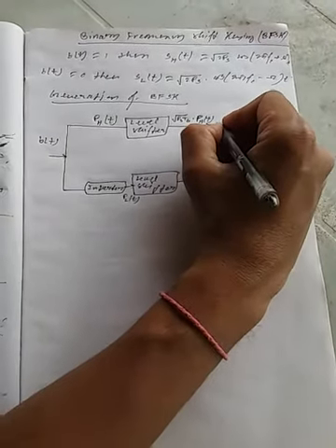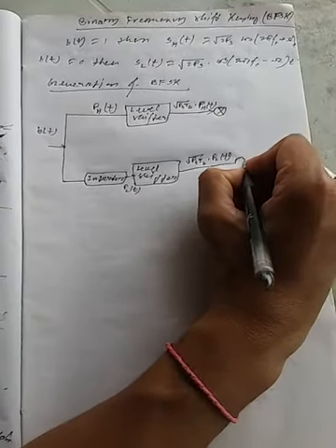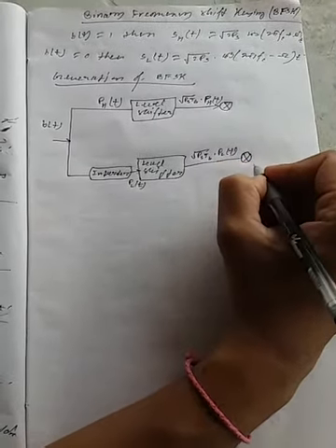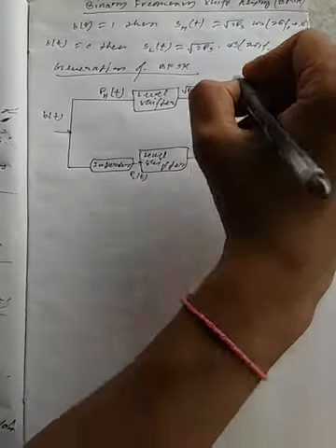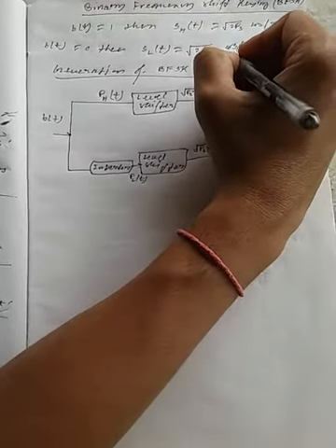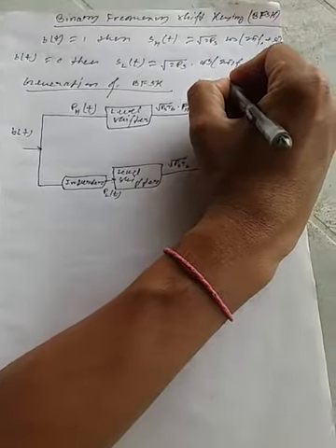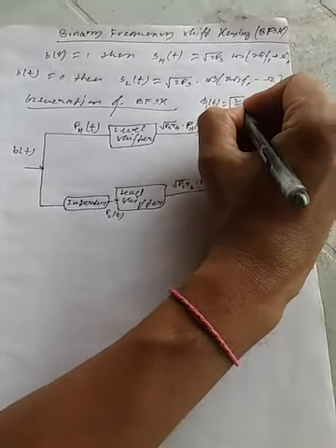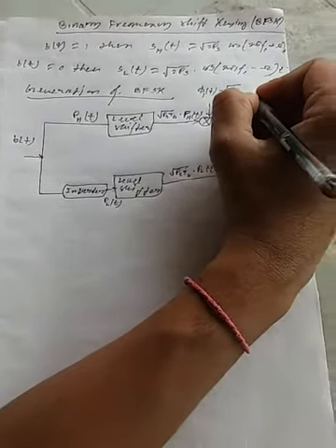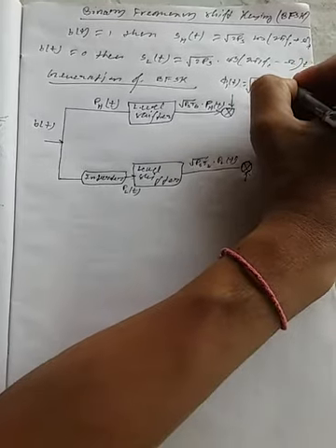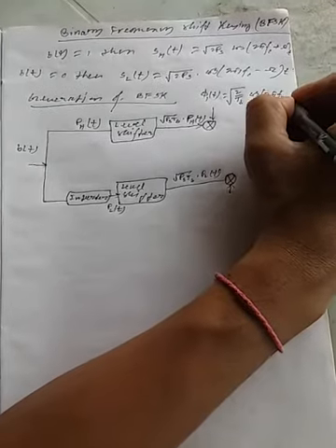Now there is a mixer here, and here is also a mixer, to mix the carrier signal. What is the carrier signal for the higher frequency signal? Suppose the carrier signal is phi 1(t) equal to root 2 by Tb, where Tb is the bit duration, into cos 2 pi fH t.